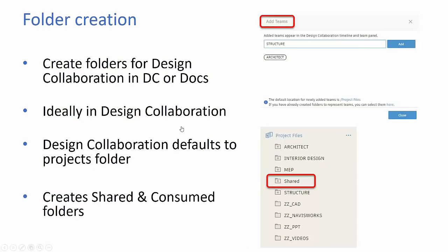Next thing I want to do here is look at our folder creation. What I'd recommend is you do this inside of design collaboration. Some customers I've met with have done this in Docs, but it doesn't create that PAS 1192 type framework with the share and consume folder. So I recommend just following this out-of-the-box 101 workflow of doing it inside of design collaboration.